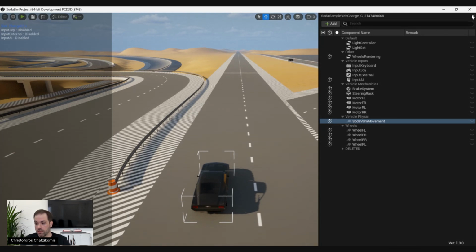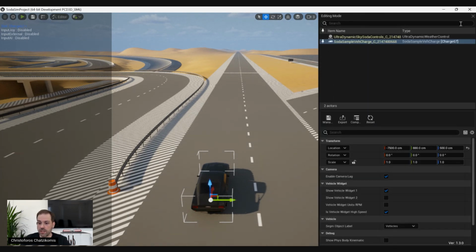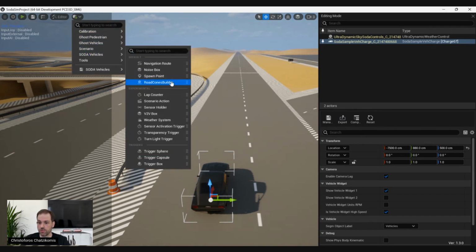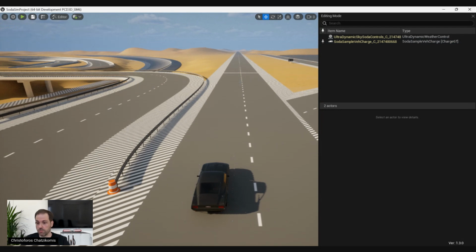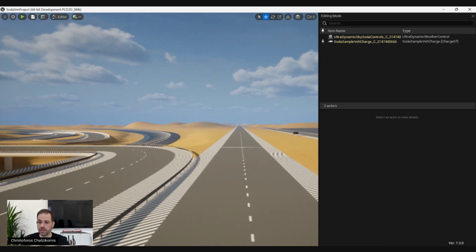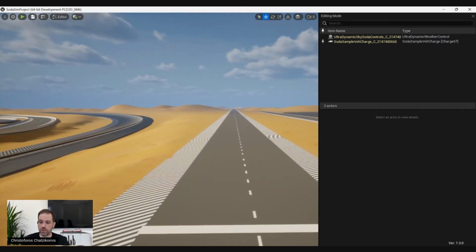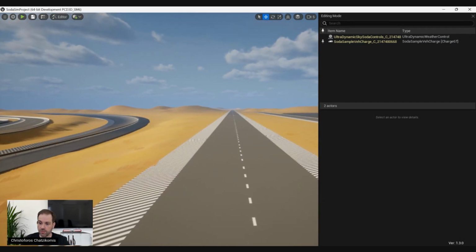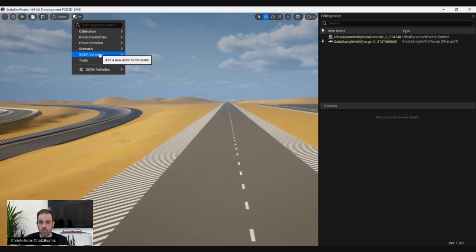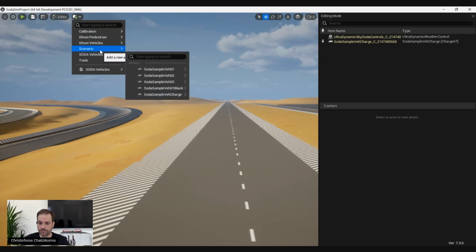So now the next thing that we need to do is set up the obstacle avoidance scenario. So for this, we can use, for example, some cones to add to the route. The obstacle avoidance scenario is a very standard test in vehicle dynamics, basically where we test the stability of the vehicle in a maneuver that simulates basically a double lane change to come to the original lane very quickly. So we will add some cones here,